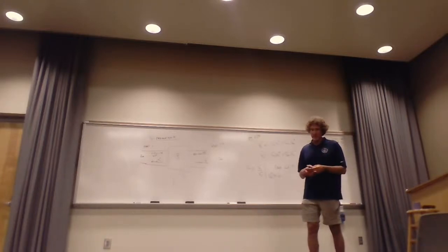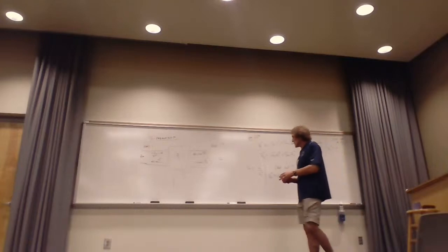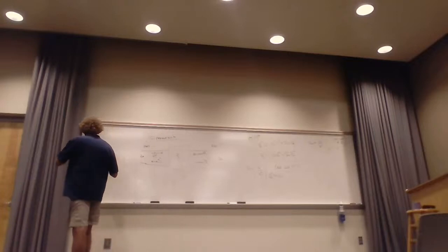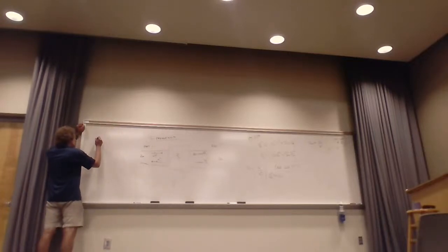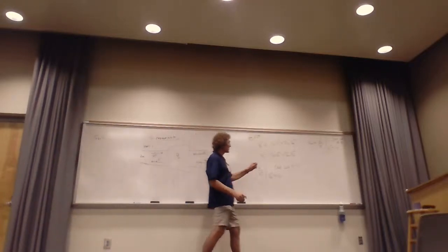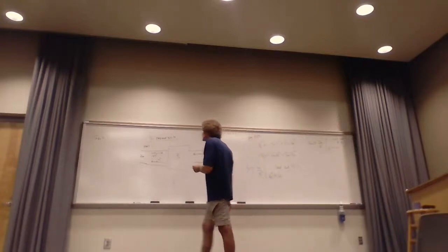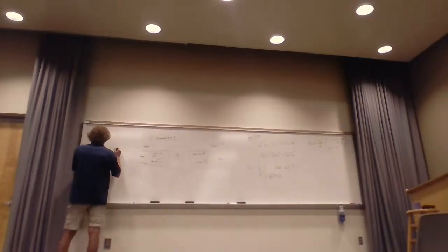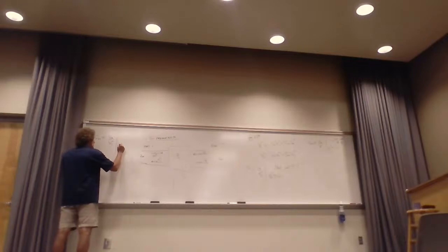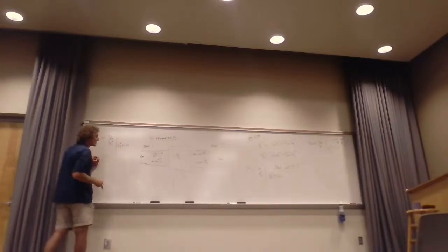So whenever we're doing S11 and S22, it's assuming that there is no reflection back from the other port. Then, when we take a look at S21 and S12, they're called the forward and reverse voltage gains. So when we look at S21 right here, that's V2 minus over V1 plus, assuming V2 plus is 0, isn't it?